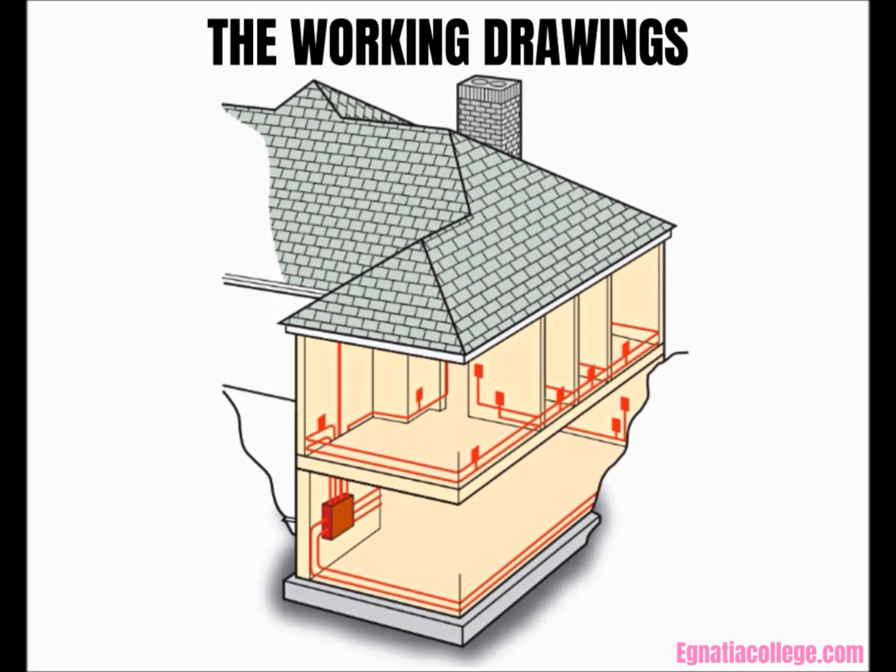The electrician must be able to convert the two-dimensional plans into an actual electrical installation, visualize the many views of the plans and coordinate them into a three-dimensional picture, as shown in this figure. The ability to visualize an accurate three-dimensional picture requires a thorough knowledge of blueprint reading. Since all of the skilled trades use a common set of plans, the electrician must be able to interpret the lines and symbols that refer to the electrical installation, and also to interpret those used by the other construction trades. The electrician must know the structural makeup of the building and the construction materials to be used.